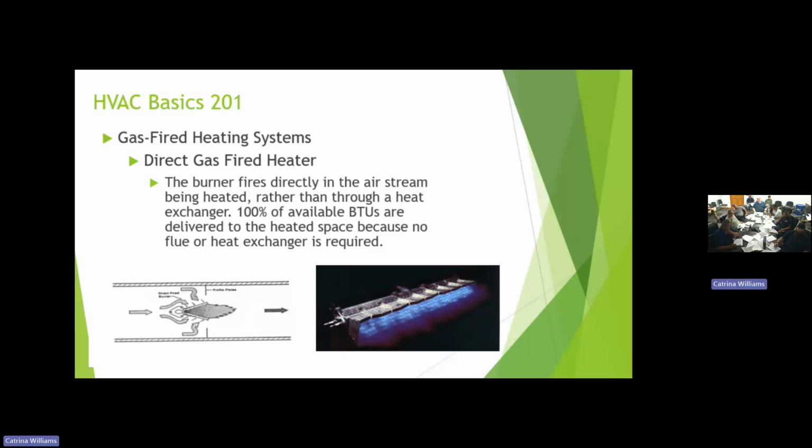So there's that, and I know you can't read it, but maybe the handouts show it. This is marked as profile plates. Every unit that goes through engineering, they size this opening based on the size of the burner and the CFM that unit has been ordered for, so they can get the right velocity going through there. So every unit is custom designed by engineering to get the right velocity across that plane. And that's why we test every unit, to make sure it's working.